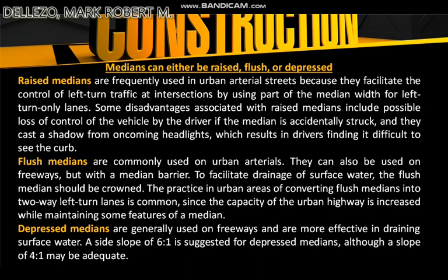Some disadvantages associated with raised medians include possible loss of control of the vehicle by the driver if the median is accidentally struck, and they cast a shadow from oncoming headlights, which results in drivers finding it difficult to see the curbs.